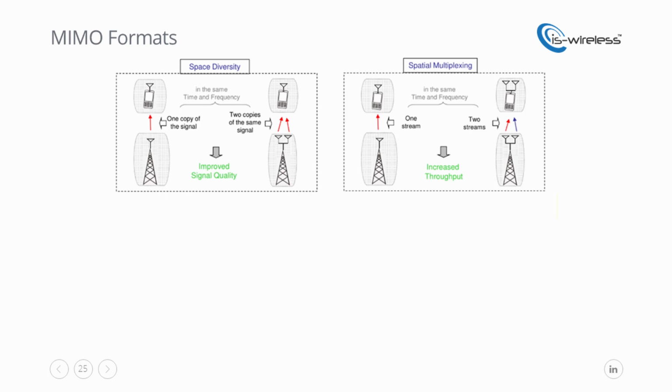In spatial multiplexing, each of the spatial channels carries independent information, thereby increasing the data rate of the system. This can be compared to the orthogonal frequency division multiplexing technique, where different frequency subchannels carry different parts of the modulated data. But in spatial multiplexing, if the scattering by the environment is rich enough, several independent sub-channels are created in the same allocated bandwidth. Thus, the multiplication gain comes with no additional cost on bandwidth or power.